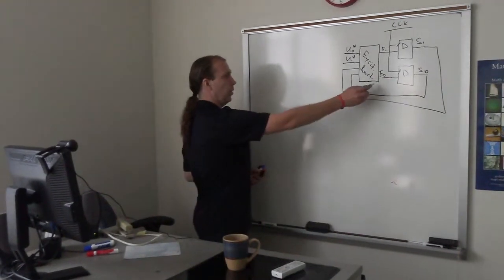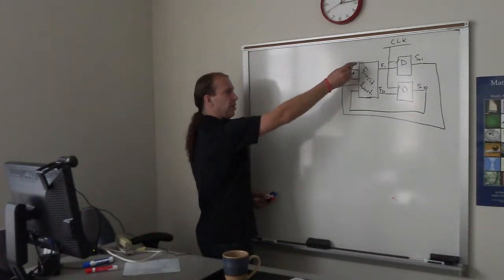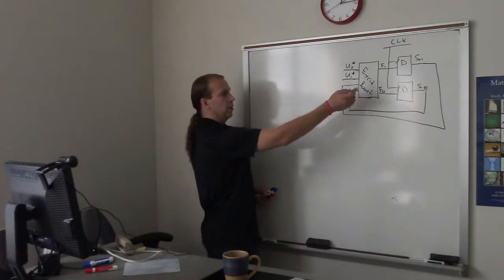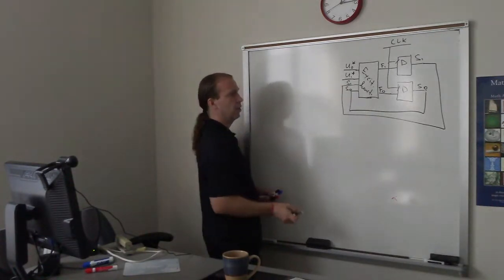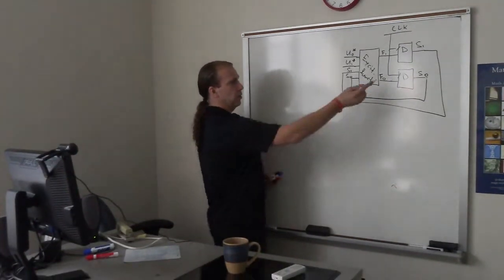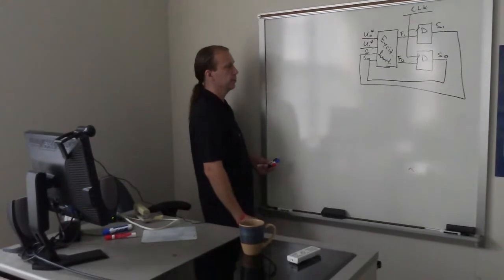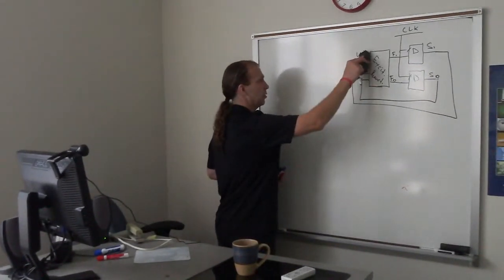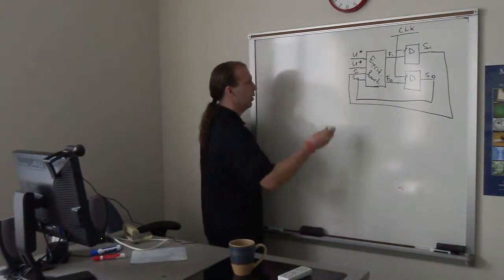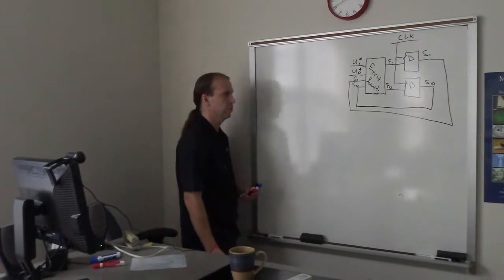Now, we want to develop that excitation function, and it looks like S1, S0, and it needs to generate two outputs. Let me use the same notation, the same order, where the most significant bit goes first.